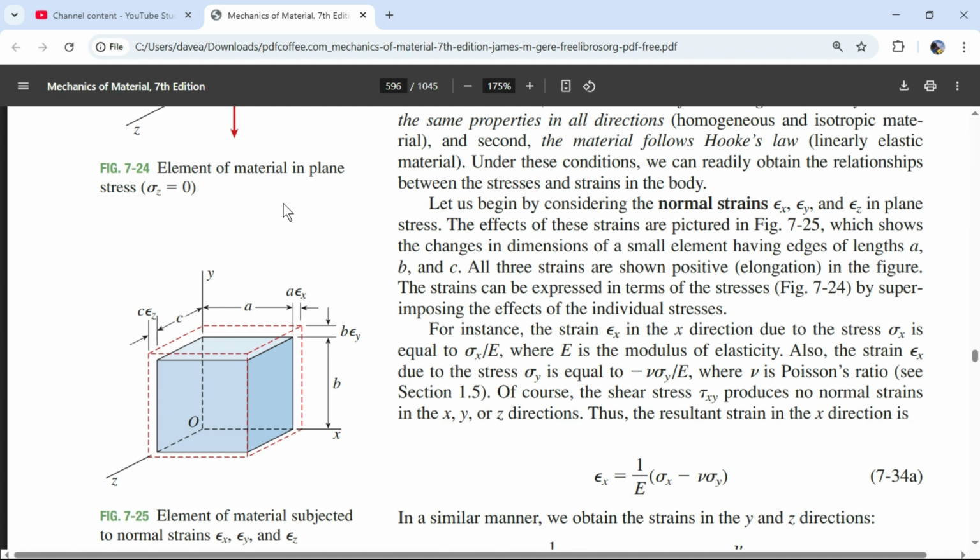That's going to be 2 millimeters divided by 1,000 millimeters. We said that steel bar could lengthen, a change in length of 2 millimeters. Its original length was 1,000. So this value on strain, and that's going to be a max strain, is 2 divided by 1,000, or 0.002.